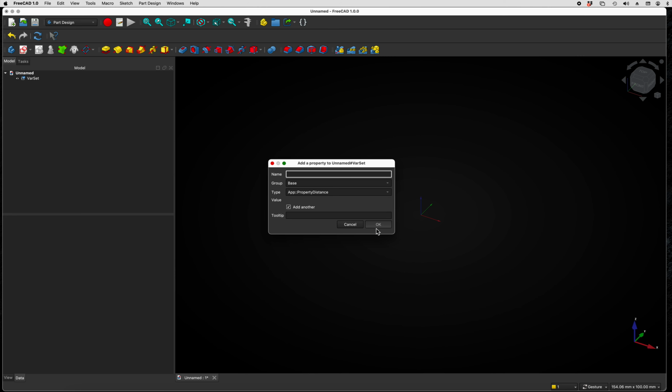Now we're going to define also the tap. The size of the tap that we're going to use on the top. As I've explained before, in 3D printing, if you create an 8 millimeter threaded rod and an 8 millimeter tap, it won't work because of the inconsistencies and the errors built into 3D printing.